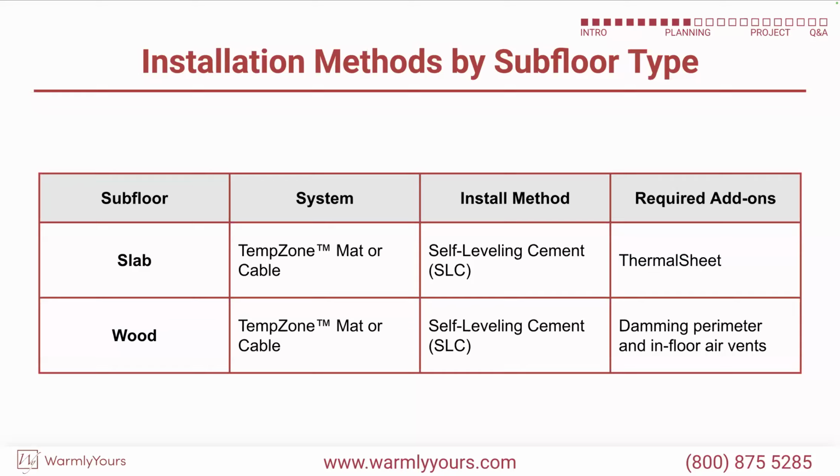So wood doesn't suck the heat down like concrete does. So that's why we're not installing the thermal sheet. That's why that 6 millimeter or 1/4 inch thick sheet of thermal sheet isn't required with wood, because it doesn't pull the heat down.